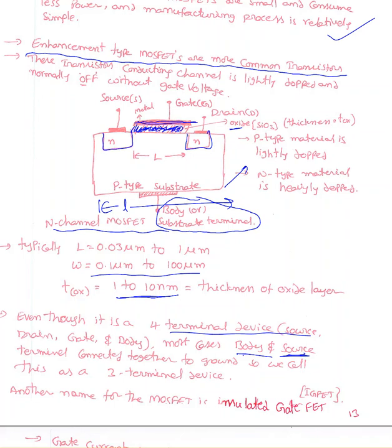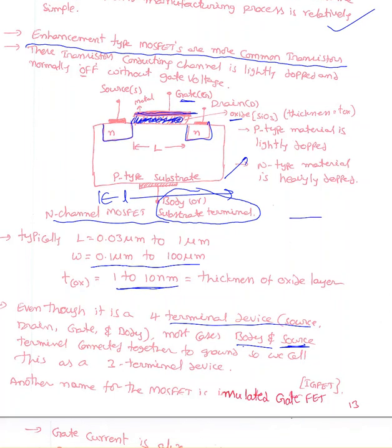Okay, so here is the oxide and this is a metal part. Whenever we give a positive supply to the gate, the metal there is going to act like a positive, so this is going to be positively charged. Now what does the p-type material have? Majority carriers are holes, so this p-type material is carrying lots of holes.